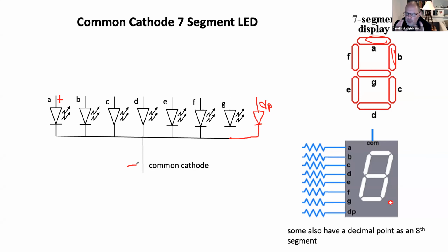So just don't be confused when we say it's a 7-segment LED, but you actually need 8 pins to program it. It's because it has this decimal point in there. If you're ever working with these, some of these are common anode and some are common cathode. The ones we have are common cathode. So you don't want to mistakenly use one and wire it up as another.